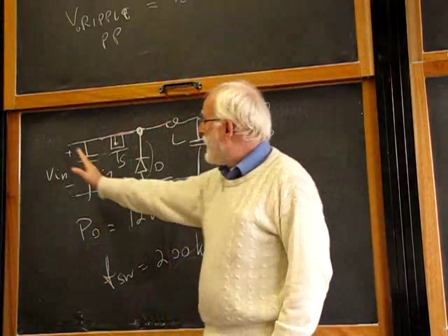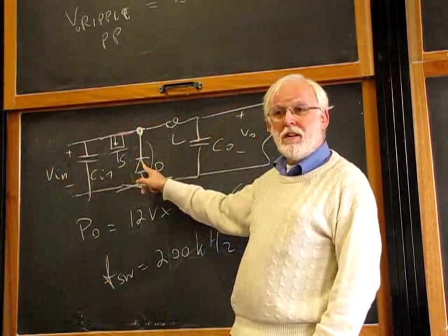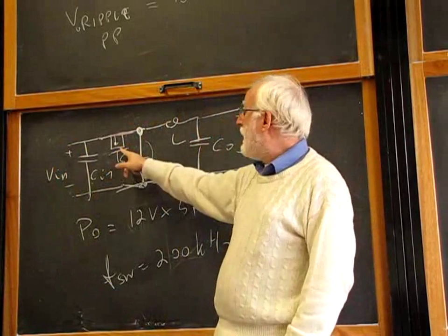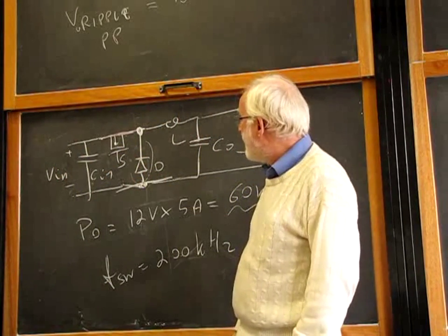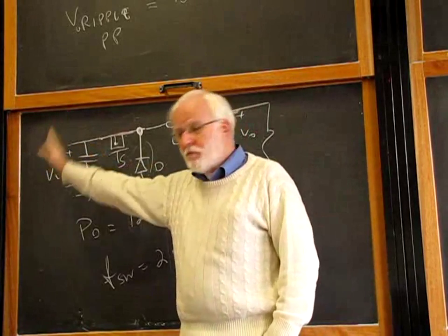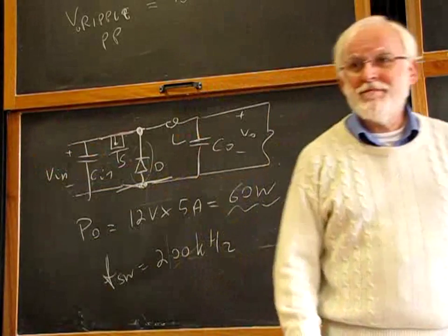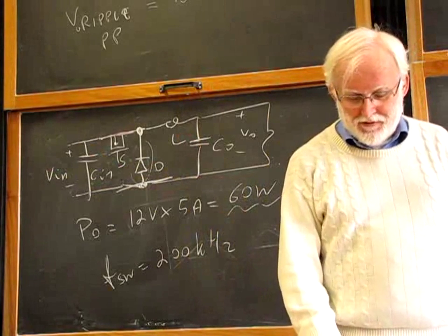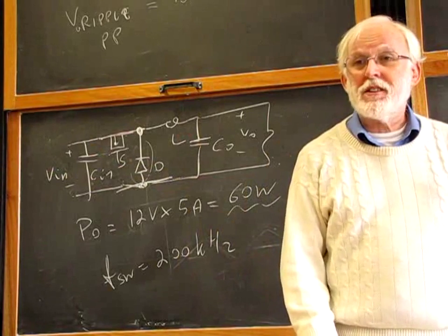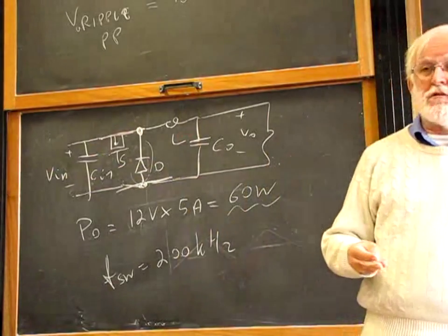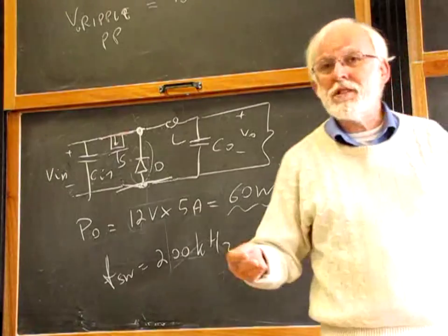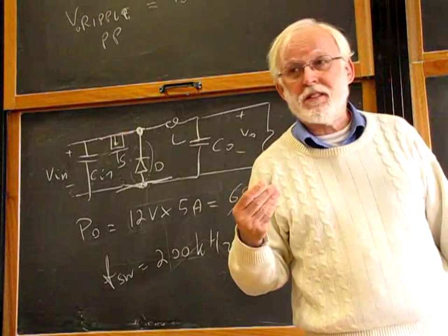If you don't have any protection over here, this diode will die, and the MOS transistor as well will die, unless you use 100 volt parts. So 40 volts, if you have protection, is okay. If you don't have protection, put that. If I remember, I will put online a link to an application note showing what are the maximum voltages you can have in a car, or the maximum voltage you can have in a house due to lightning, to the electric thunderstorm around, etc.